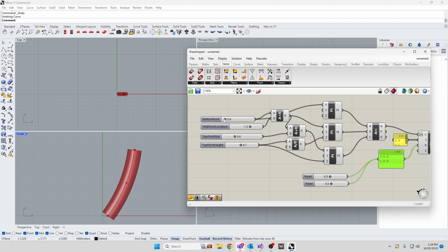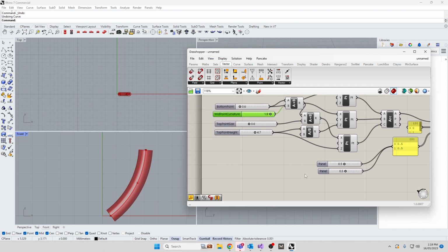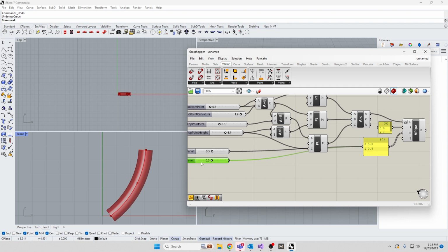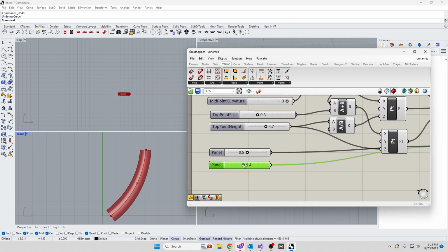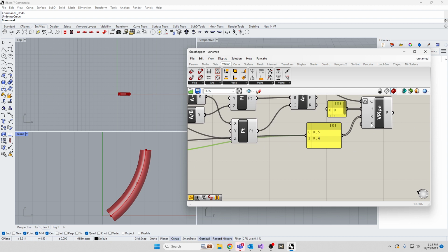Now this will follow, the whole part will just keep redrawing itself as we need. Oopsie, my bad. Okay, so you get a little bit more curvature. You can also change the ends of your item. Alright, so then to wrap this up very quickly, this is your bottom point diameter, that's your top point diameter for the support. The last thing we know is that we want it round, okay, and normally your tip diameter is a little bit smaller. So there's a parameter inside here, the end cap, you can set to round.